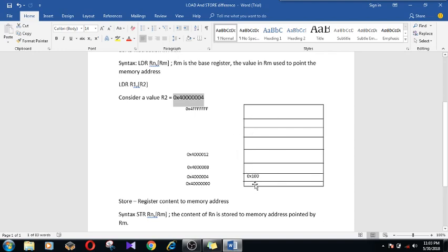You can see here that for each segment a specific address has been provided. Among these many addresses, you are interested in the specific address 400004. To pinpoint a specific address location, you load that into the RM register. Here RM is replaced with the R2 register, so R2 points to where this address is located.